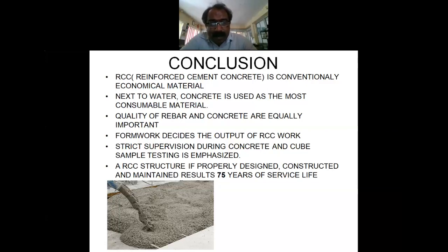Next to water, concrete is the most consumed. The quality of rebar and the quality of concrete are both equally important. The formwork decides the output of the concrete works, so good formwork should be used. Strict supervision during concreting and cube samples. Every concrete is to be tested with cubes.